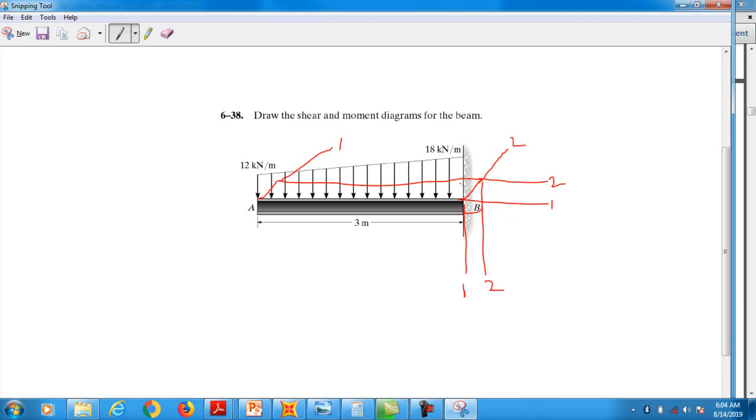So the number of grid lines in x direction is 2, and in y direction 1 or 2, both work, since we have only one axis there. In z direction we just need to draw a line element, not a 2D element, because we don't know and don't need the height of this beam.